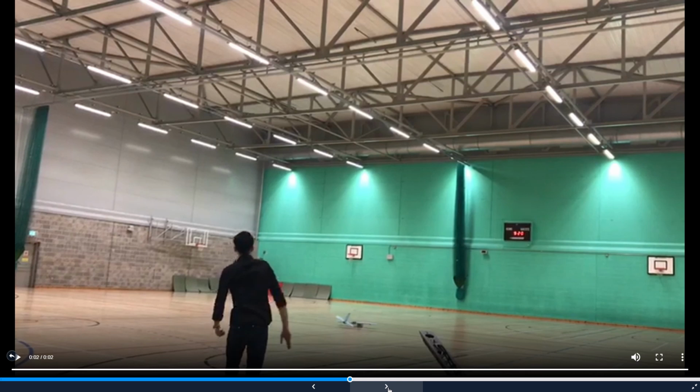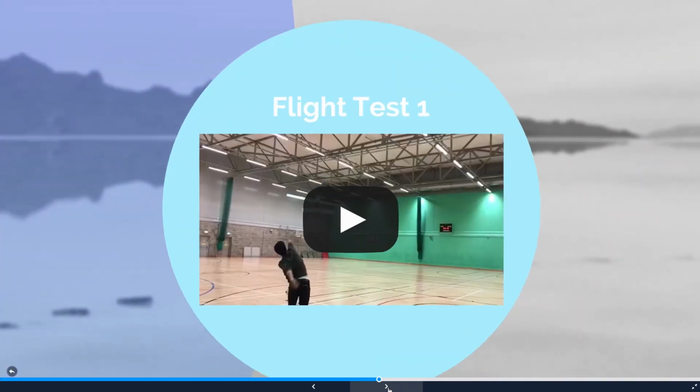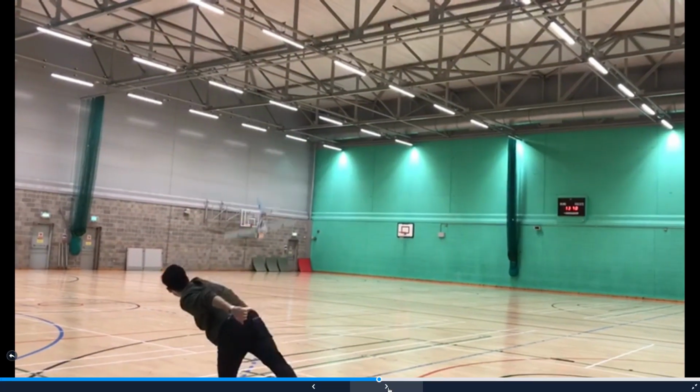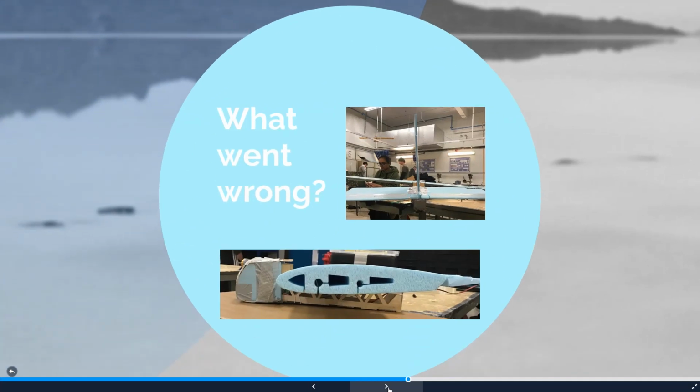For the official flight test, we attempted to incorporate thrust generation during flight. In flight test 1, the UAV landed heavy due to a negative wing setting angle. This was a construction error which compromised the flight performance. Also, the fuselage structure was too bulky, which contributed to the excessive UAV weight and blocked the oncoming air, reducing the amount of thrust generated from the propeller.